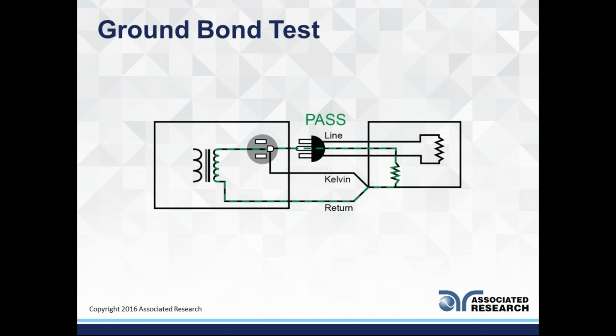Now it's important to note that in real world testing, these won't look like two wires. They're shorted and coated in the same wire, so it'll look like one thick wire, but we want you to understand what's inside of there. It's a 4-wire Kelvin connection, which is offsetting any resistance coming from your test apparatus or your test wires, or even internal resistance of your testing instrument.